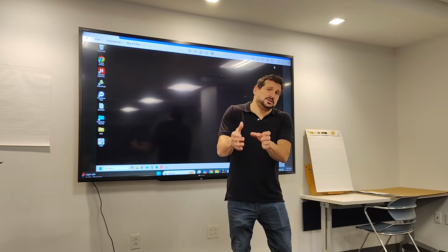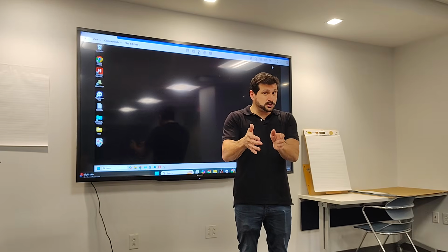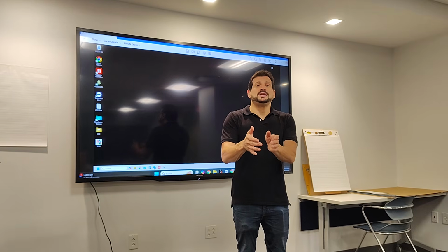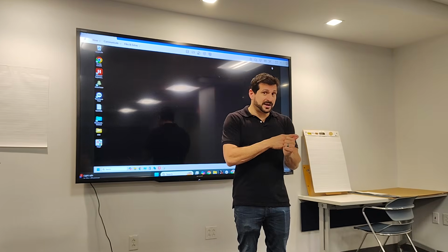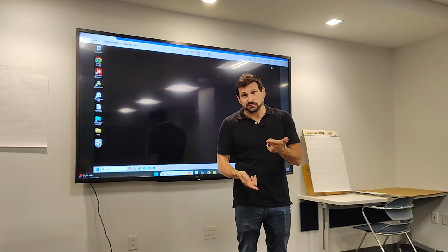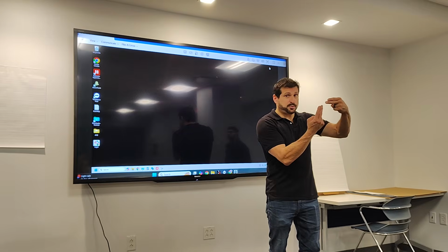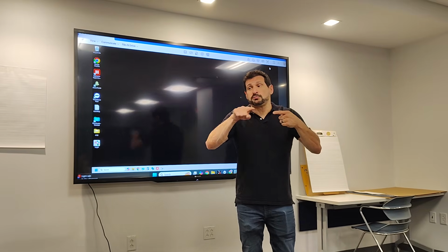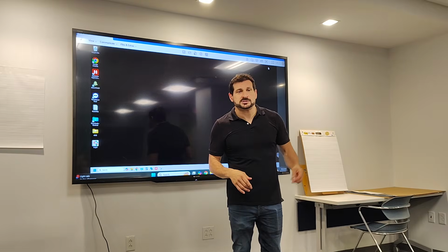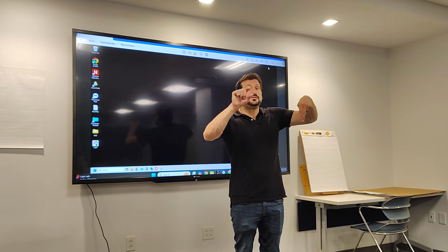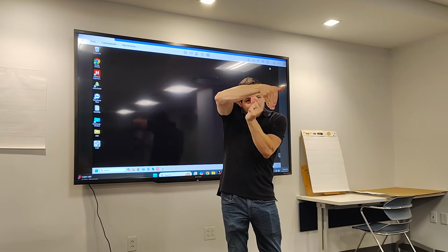So you can adjust an output, and the system will allow you to adjust those outputs, but once you adjust an output, you've overridden it, which means it's like that until either the override falls off or you select the override to fall off. So I have an input of 65 degrees. I have a set point of 72, but someone overrode that valve to closed. The BMS says open, but the valve's not going to open. Even though the program wants it to open, you've got in the middle. You stopped it, you overrode it, and now you're telling it what to do.